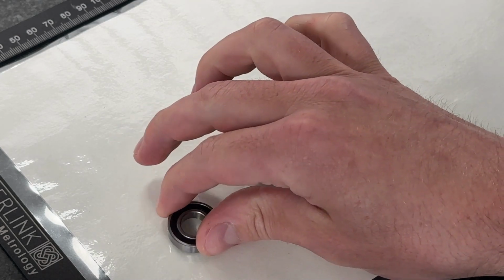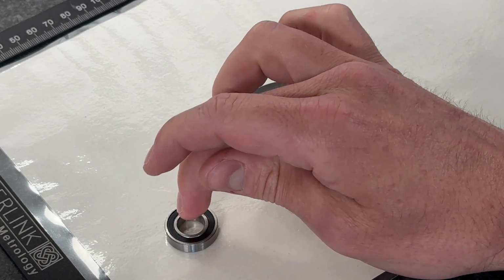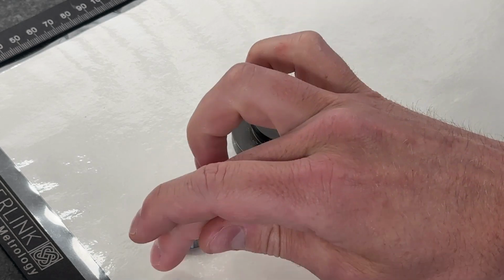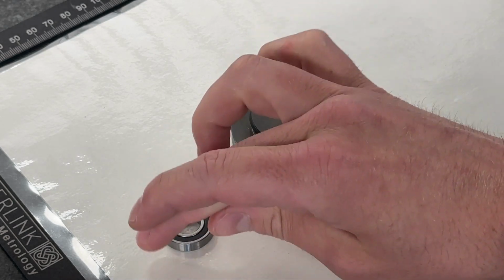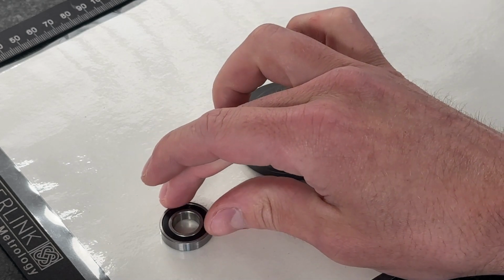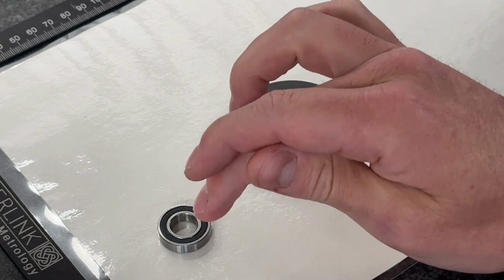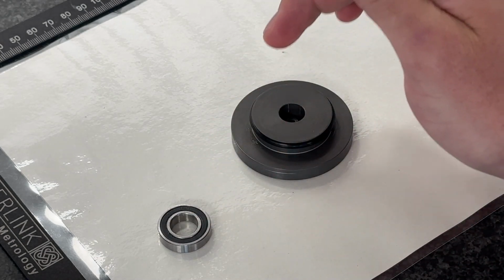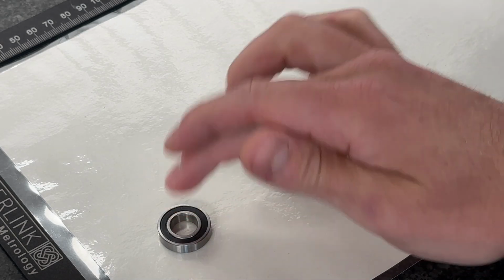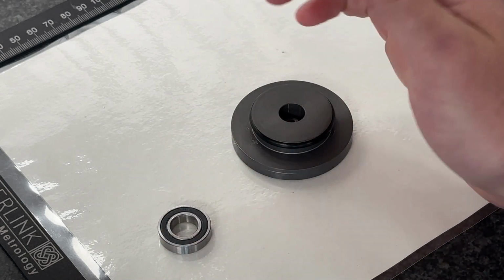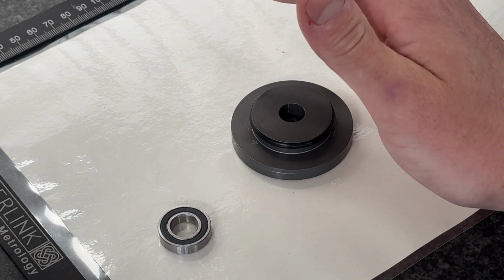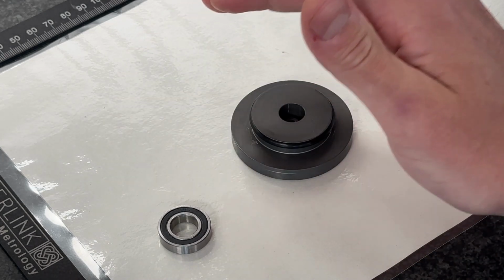So this is a good example, where the two circles being checked to each other are measured or projected at the same height. You can imagine with this bearing, we'd have a plane, we then measure the internal circle, then the external circle, and the measurements would be taken at pretty much the same height. So there's no height differential that is going to cause the measurement to be skewed. The same with the plane, they'd both be projected into the same plane, meaning there's no skewing of measurements from one plane to the next.